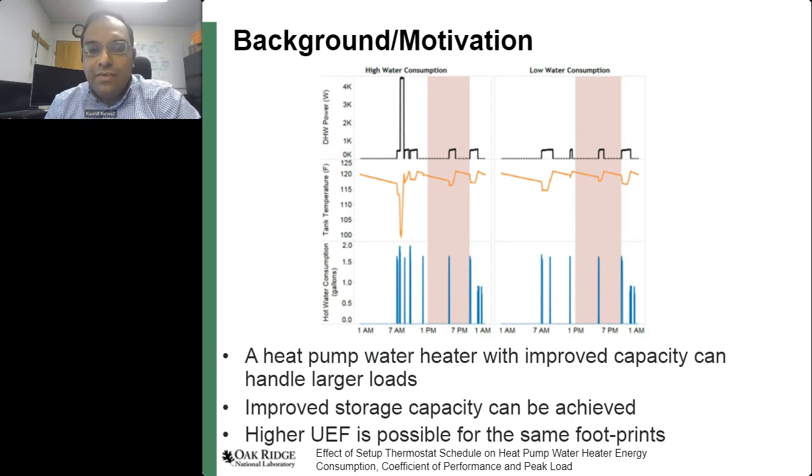In terms of COP, we have observed that heat pump water heaters have more than 3 COP, but in the case of electric heaters, the maximum we can achieve under the ideal case is 1. So for the overall operation, if we can reduce the usage of any ancillary heating and really rely on the heat pump system, that can have significant energy benefits.